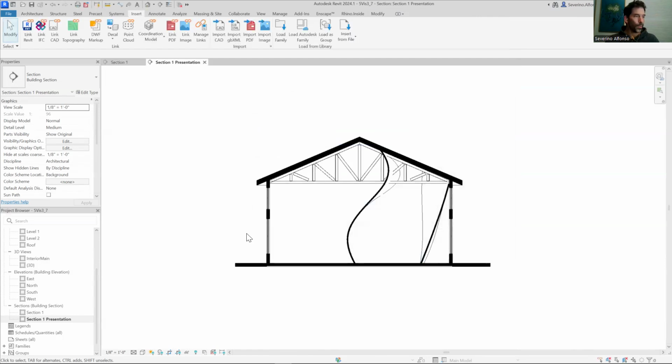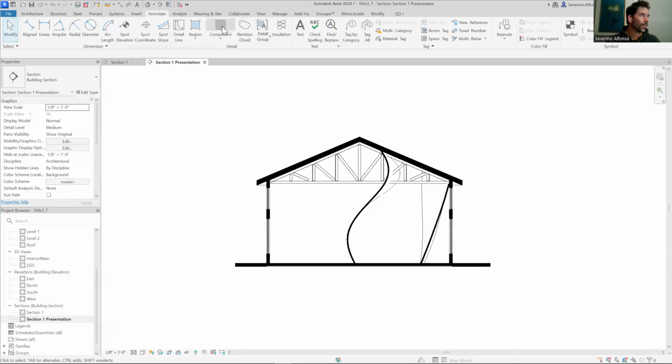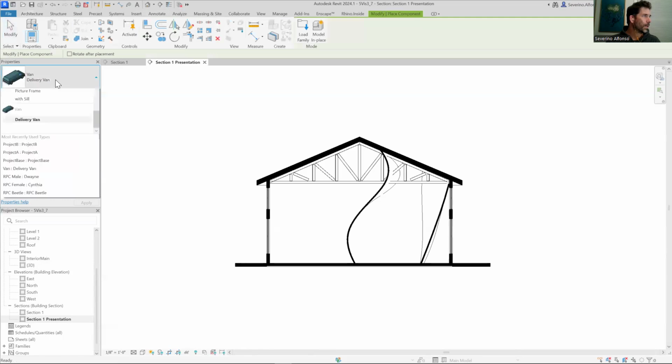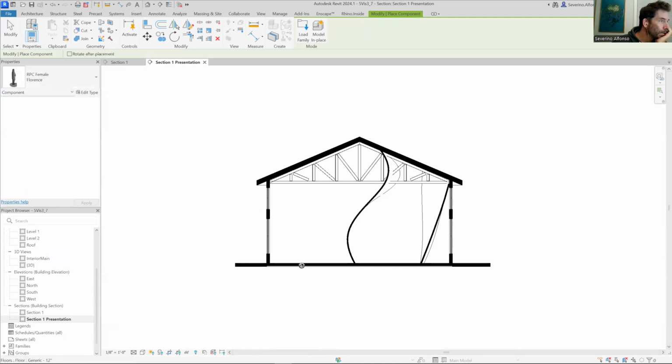And then the question is, how do you bring those to the drawings? You can click here if it's three-dimensional, or if it's an annotation, you will click here for two-dimensional. So under architecture component, and the newest material will be here. So you can find the trees that we mentioned, and also the persons that we just discussed.